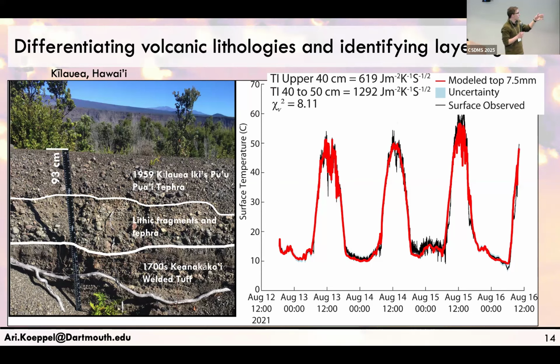We looked around. We had taken a bunch of pictures in the field, and we noticed that at some of these embankments, there was distinct subsurface layering. So we thought, why don't we add another layer to the model and also have an adjustable depth between those layers? And it turns out when we did that, the model produced a much better result, a much better fit. And it actually matched what we were seeing in the field.